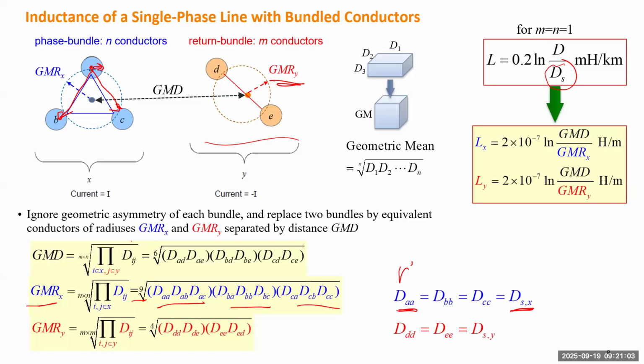So you see, by using this example, we can explain that when you calculate the GMR for each group, you use each one as a reference. You consider the radius on its own and the distance to anyone in the same group. Then you change the reference to another one. Finally, if I have 3 elements, that will be 3 by 3; 4 elements will be 4 by 4.